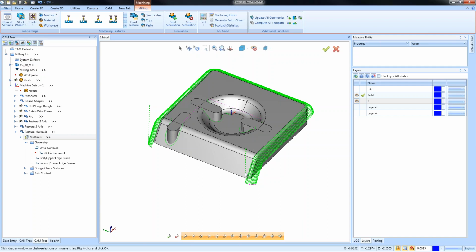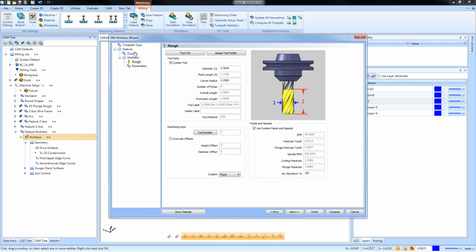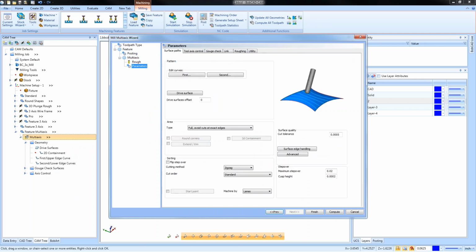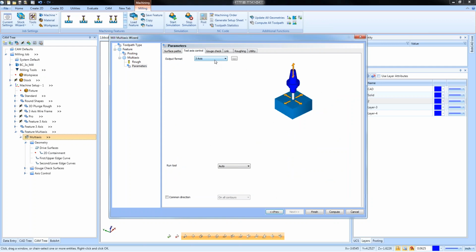Looking for more advanced 5-axis? Absolutely, Dustin. We'll probably get into more 3+2 and some of the basic 5-axis before we get into more of the multi-axis package, just 4-axis or both 4 and 5-axis. This particular toolpath could be used for 3, 4, or 5. If you're a Mill Premium user on the tool axis control, it'll be limited to 3-axis. If you're a 4 Pro user, you'll get it for 4-axis. If you're a 5 Pro user, you'll get it for 5-axis. So 5, 4, 3 down the line.